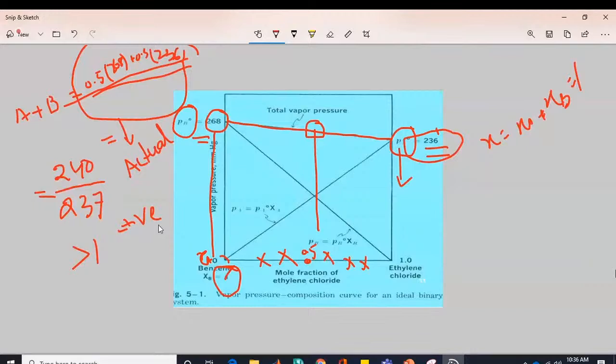The pressure exerted by the vapor above the liquid is much lower. At very low pressure, the distance between the evaporating surface and the condensing surface is approximately equal to the mean free path of the vapor molecule. I hope you're aware about the mean free path of the molecules.